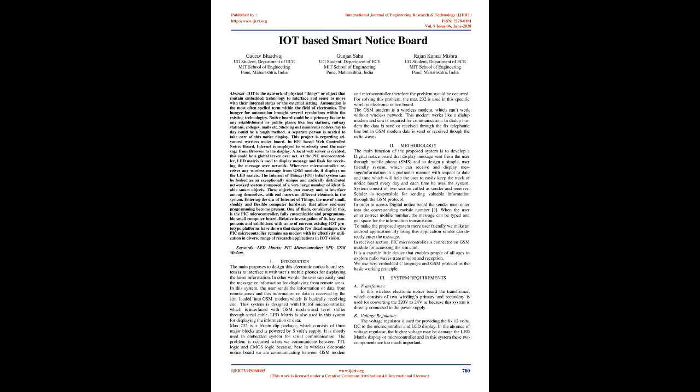Keywords: LED matrix, PIC microcontroller, SPI, GSM modem. Introduction. The main purpose of designing this electronic notice board system is to interface it with users' mobile phones for displaying the latest information. In other words, the user can easily send a message or information for displaying from remote areas. In this system, the user sends the information or data from remote areas and it is received by the SIM loaded into the GSM modem, which is basically the receiving end.